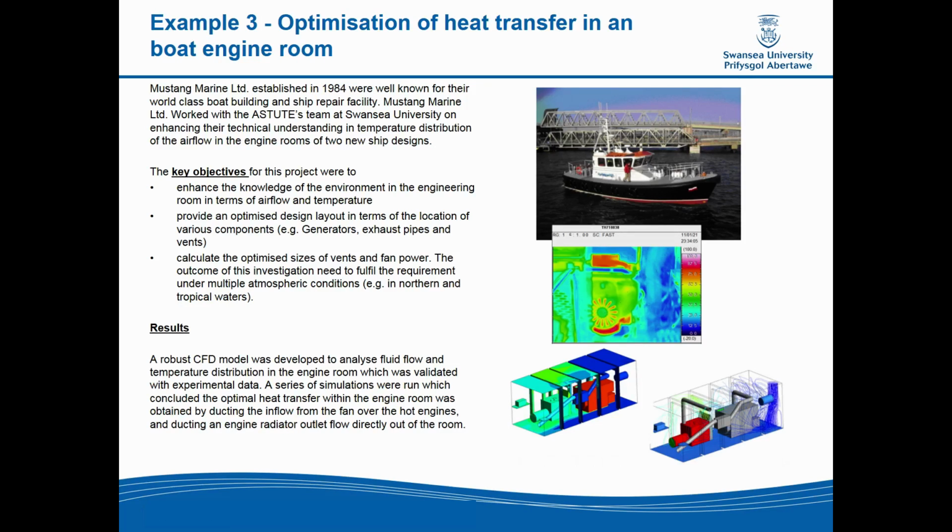Another one, which is thermal fluidic. So this is looking at the position of the engines on these ships. This is a company which has sadly gone out of business now. I don't think it was our fault, but when we did the work for them, it was an interesting use of CFD, and the guys who were running the company were very interested in the results. It was being able to locate the twin engines that they had inside the engine rooms in such a way that you kept the intake for the engine at a sufficiently cold temperature. What they were finding is that their ships were incredibly efficient when they went up north towards Greenland, but when they went south down into the tropics, they lost all their efficiency. And so they were looking to try to optimize the location of the intake air.